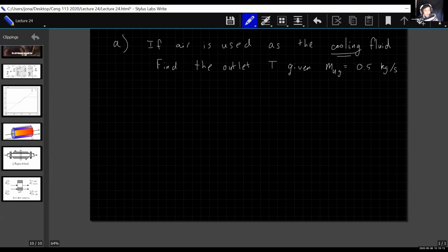So if you're one of those people who are prone to errors in MATLAB that aren't making sense, if you haven't already, try doing all the calculations and equations on paper first. As we do it in MATLAB, because we generally recommend starting with your energy balances and defining the equations backwards, I'm going to do the same thing on paper here. Starting with the energy balance of our utility, we can define this simply as the expression dT/dV is equal to negative del Q divided by N_U C_PU.